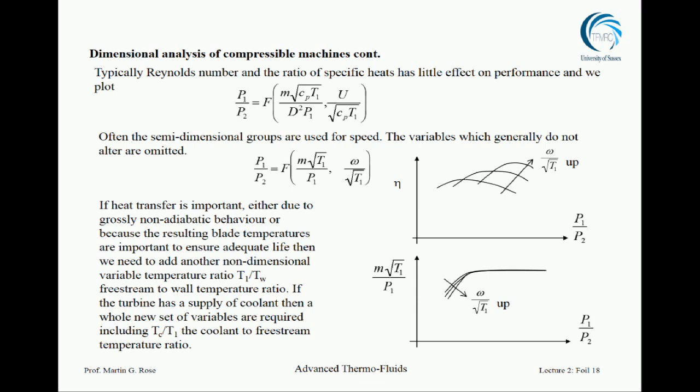And at Mather and Platt, when I was working in Manchester, they got in trouble for exactly this reason. They were selling pumps to pump oil, and the pumps had been developed and tested on water. And they did not make the correction for the difference in density between the oil and the water. Now, when you hear it, it's obvious, and they should have done it, but they got it wrong. And the consequence was that the pumps only generated 80% of the pressure rise they should.